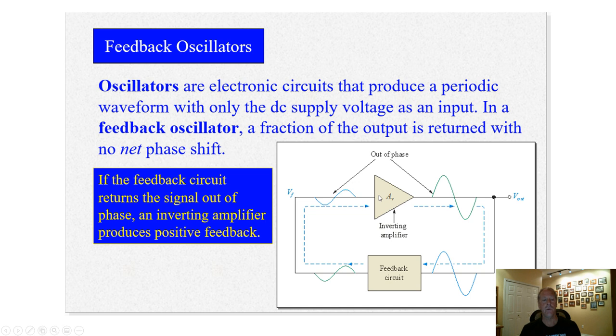Now there are two important things here. One is that this inversion happens and it gets inverted again. If it didn't get inverted again, the signal would die, because it cancels itself out. So you can't have that. It has to be non-inverting all the way around, in other words, 0-degree phase. As a matter of fact, it can't even be out of phase. It has to be completely in phase between input and output. The feedback cannot be out of phase, otherwise the signal will go away.